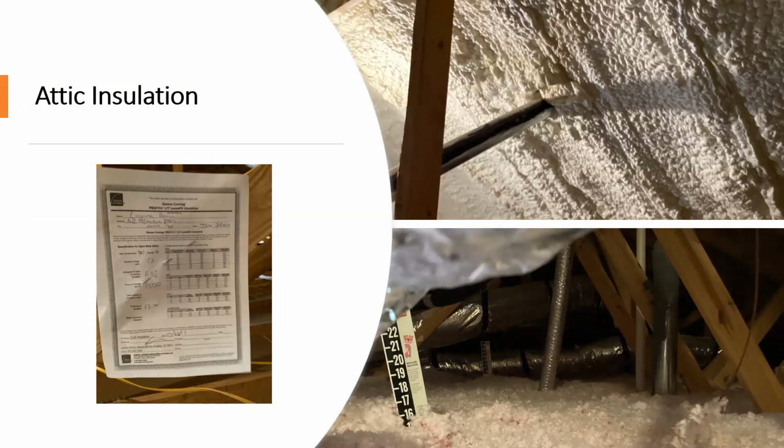Attic insulation as well. We talked about this, looking at that, determining it, having the liability of having a certification from the installer. Code requires it to be posted immediately after installation of the material. So if you're doing foam, I need to see a certificate at pre-drywall, posted immediately after install, that shows me what I'm supposed to be looking at.